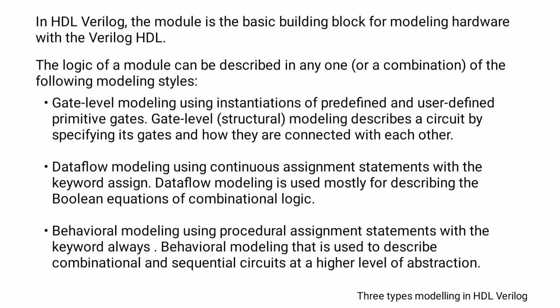In gate level modeling, predefined and user defined primitive gates are used. Gate level modeling describes a circuit by specifying its gates and how they are connected with each other. So for this kind of Verilog programming, we need to know the circuit diagram properly, which gates are there and how they are connected.